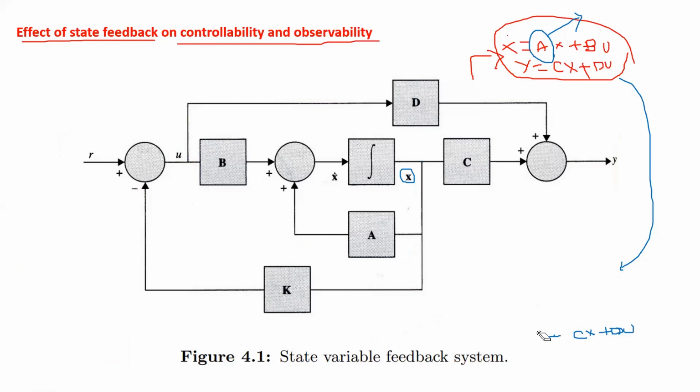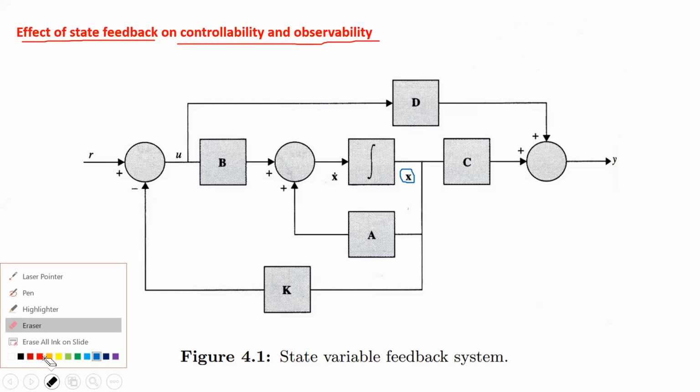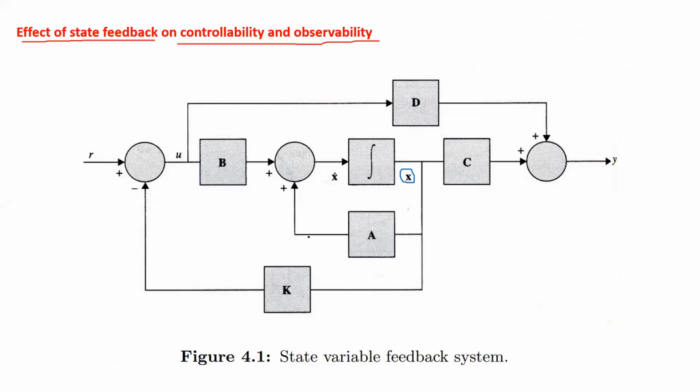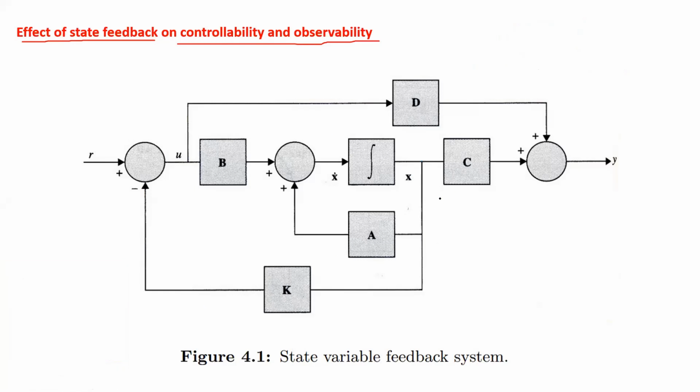Right? For a stable system, how to calculate the value of gain constant K and how to design a state feedback control. In this process, the closed loop poles are given, and we are going to find the gain matrix K with respect to the given closed loop poles. To design the state feedback controller, sometimes called SFC, the gain constant is what matters, because based on the value of K, the pole locations can be changed.